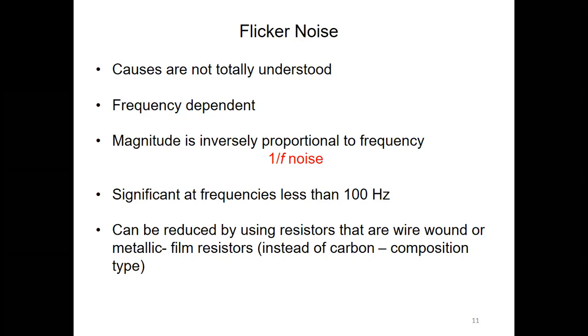Therefore, we cannot call flicker noise white noise, since it is frequency dependent, right? The magnitude of this flicker noise is inversely proportional to frequency, that means 1 over f.